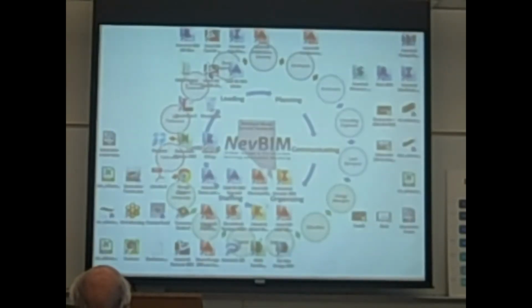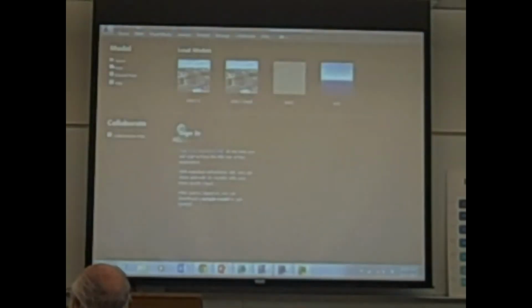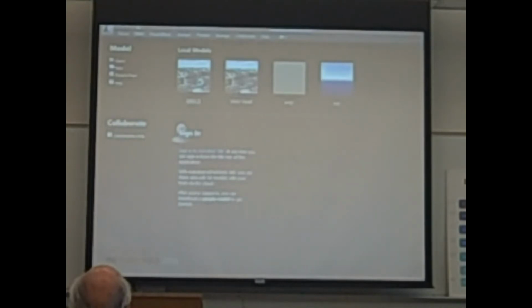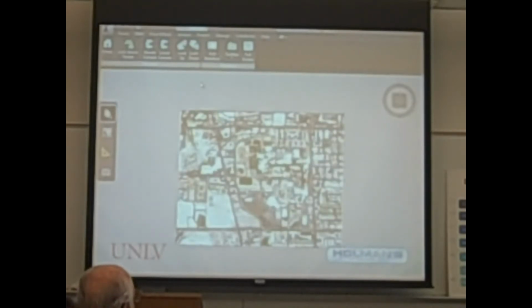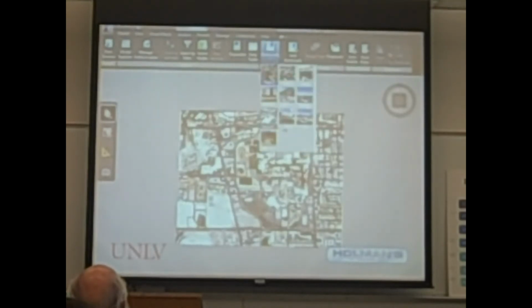All right, another piece on the project turnover, we talked about InfraWorks. So let's get back into the big model. Now out of Navisworks or out of Revit, whatever the culmination of the entire design and construction team ends up being, we can use an FBX file as sort of geometry plus materials. It can also bring lighting, but we typically don't need it. And that becomes another way to exchange information quite a bit.